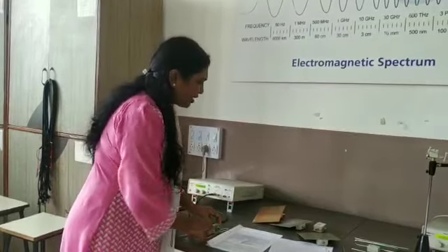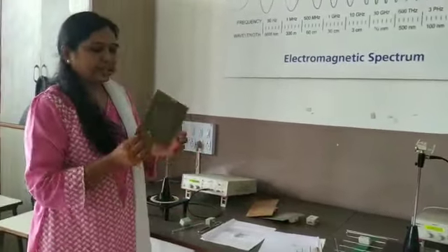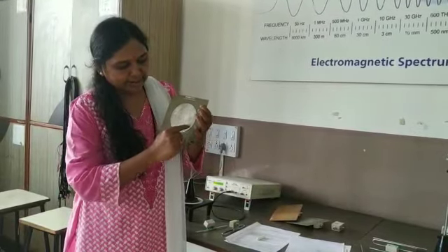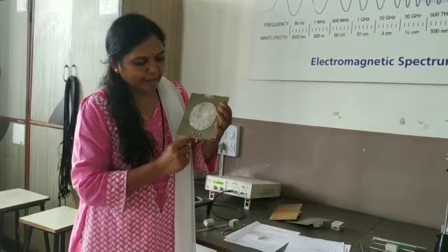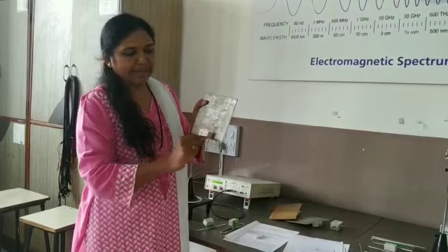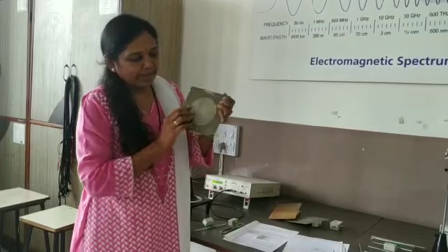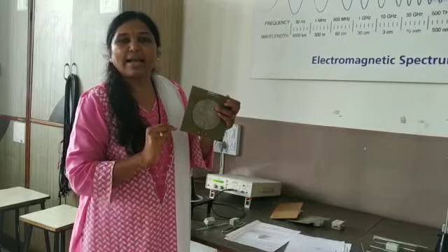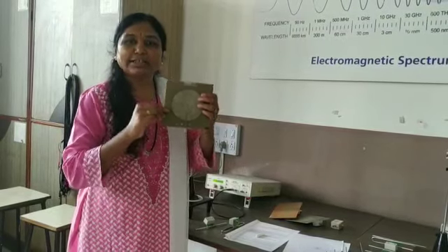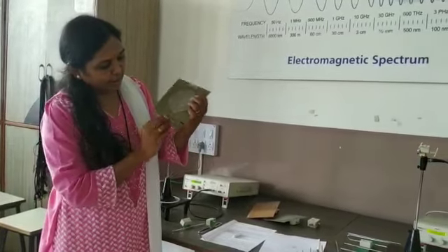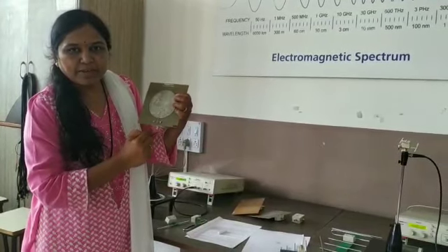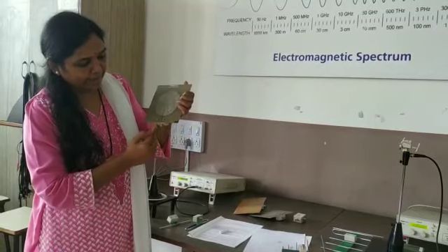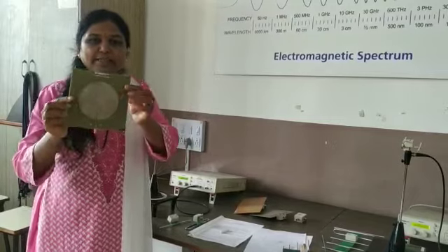Then there are some different types of antennas also. This is called a microstrip antenna. In a microstrip antenna, this is a microstrip patch, a circular type microstrip patch, and this backside is called a ground plane. In between the patch and ground plane, this material is nothing but the dielectric material, which is called the substrate of the antenna. Then this line is called the feed line for the antenna. With the help of, again, a BNC connector, we can apply the excitation signal to this antenna.